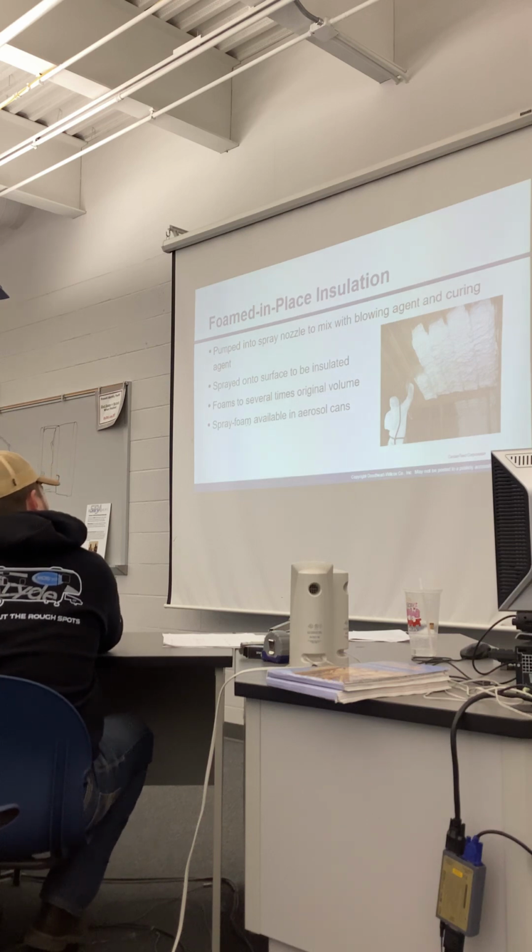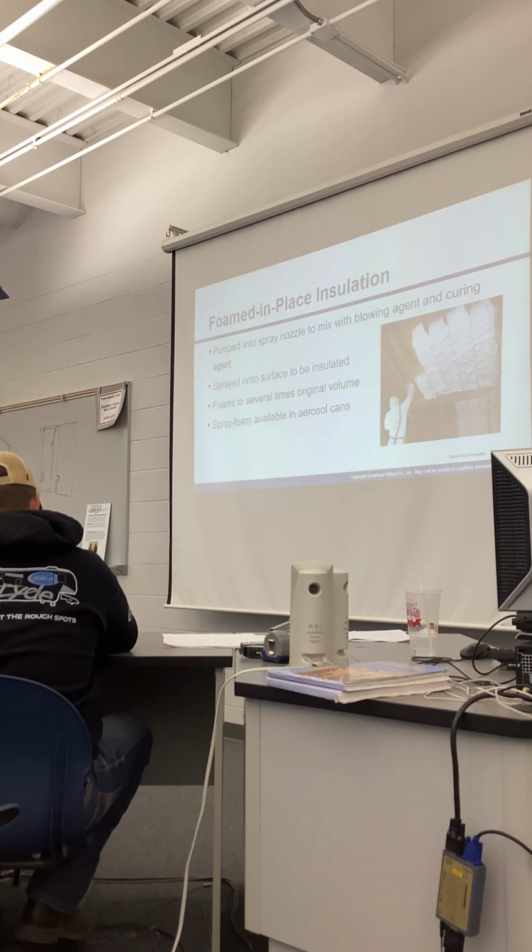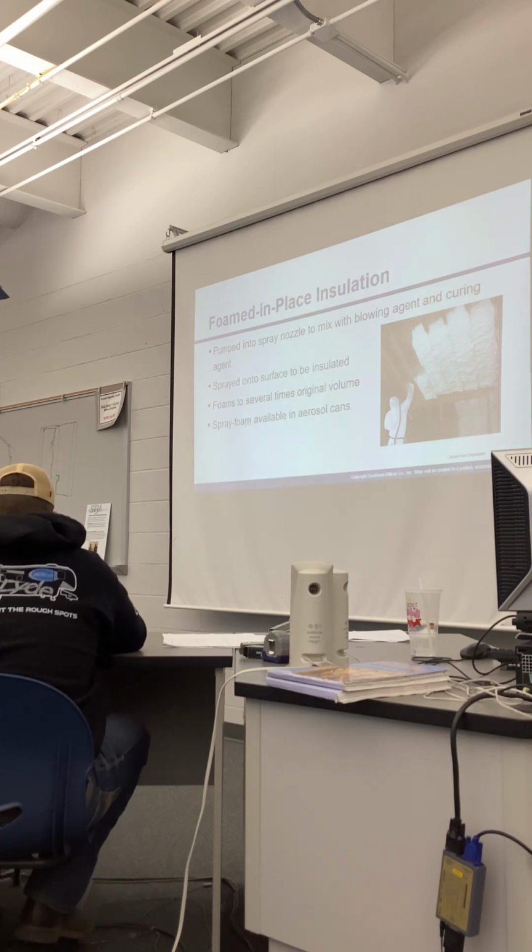You have too much moisture in your house. So then what do we do in those cases? We put dehumidifiers in our air conditioner systems, and we put outside air handling units that bring in X amount of outside air, and then we exhaust a little bit of inside air out, and so we can exchange the air in the house. But foam is a very good product because it does seal up. It is a vapor barrier. It doesn't move. It's permanent.